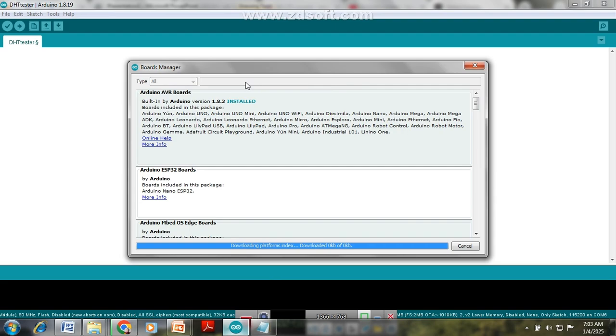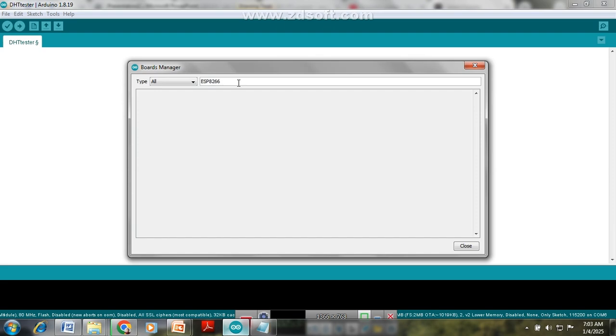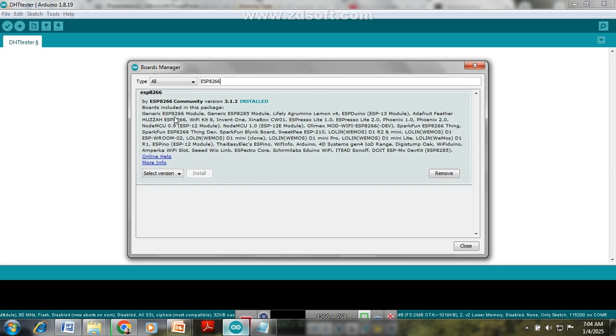It is taking time. After this, the 8266 has to be installed. Go to the Board Manager and type ESP8266.